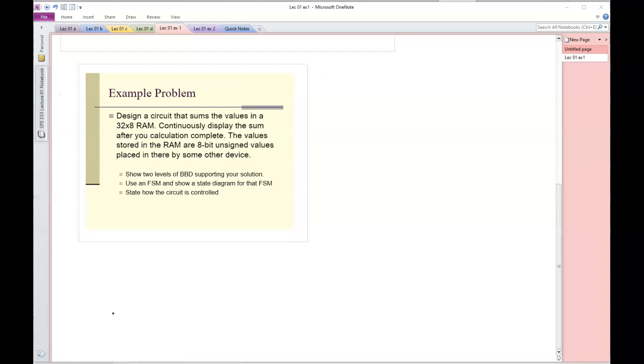support 32 times 8, which is, I have no idea what that is, but as far as we're concerned, we can do this in binary. So 32 equals 2 to the 5th. Essentially what I'm going to do is 2 to the 5th times 2 to the 8th. 2 to the 8th is essentially the biggest an 8-bit value can be, which is 256. It's actually 255, but this is close enough, equals 2 to the 13th. So what we're interested in there is that value of 13.